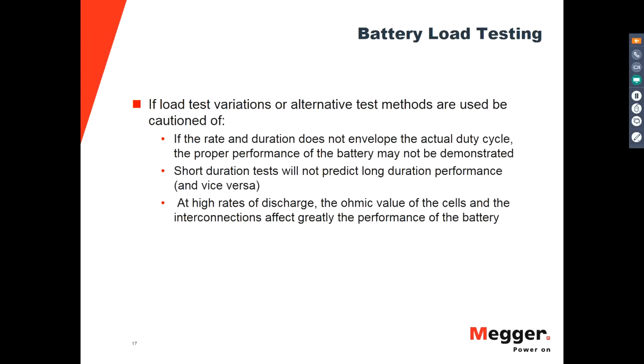And then, again, if you use any alternative methods and you select a rate duration that does not include the actual duty cycle, so basically it has to be similar or higher than the duty cycle duration, then the performance of the battery may not be fully demonstrated. The other way to say this is that short duration tests will not predict the long duration performance, and vice versa.